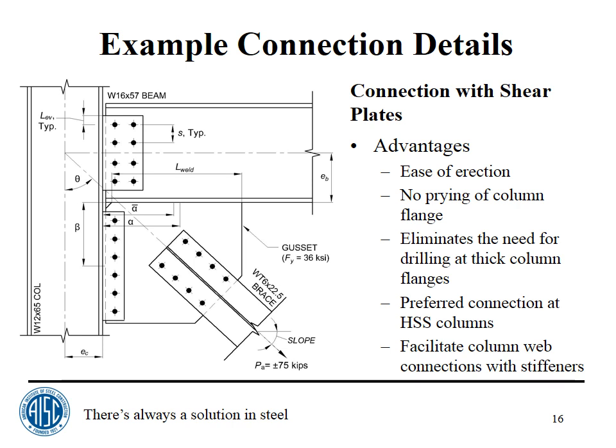Oh, we're talking about, let us say, shear end plates? Yes. With, let us say, four columns of bolts, two columns that are close to the web of the beam and to the gusset plate, and another two columns of bolts which are outboard of those two, because we've got a column flange that's wide enough that we can get four bolts across. Yes, the question is how are the outer bolts affected by prying?